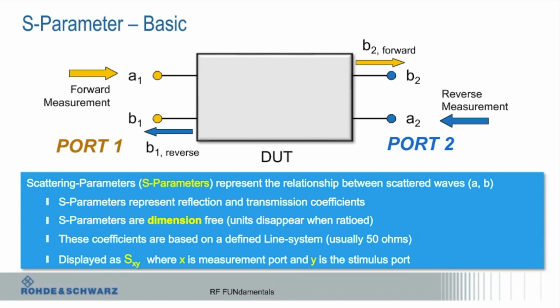So guys who are, for example, characterizing components, generating S-parameter modeling files, really want utmost accuracy, right? Those guys typically will calibrate at a more frequent interval, but the best thing to do is to have a verification device. We actually make verification kits, but it doesn't have to be a verification kit. It's basically a device with a known S-parameter file or set.